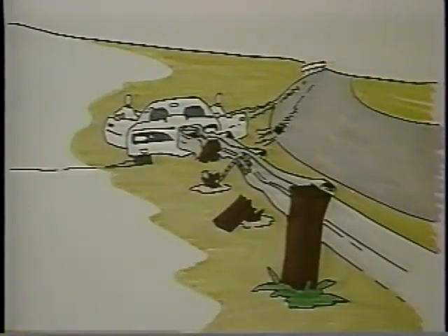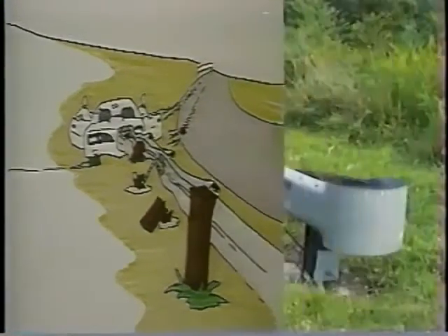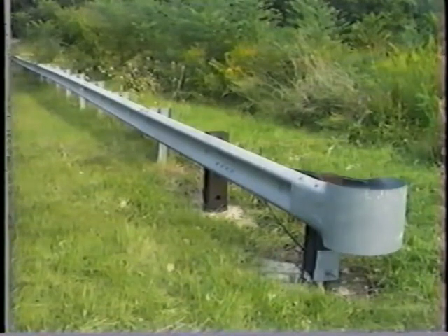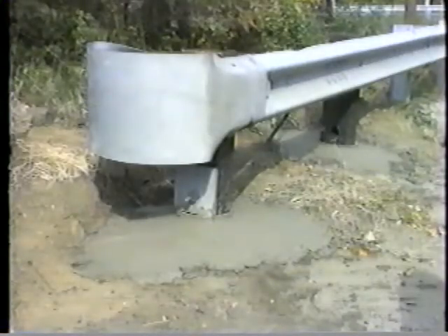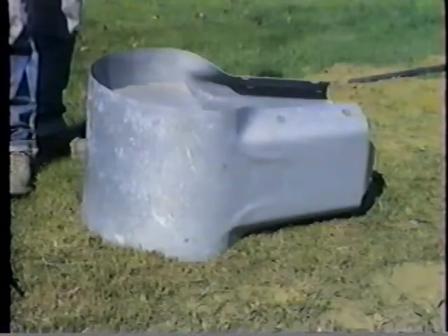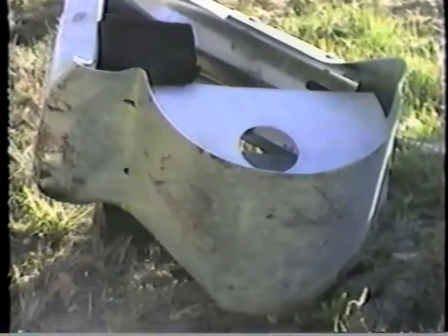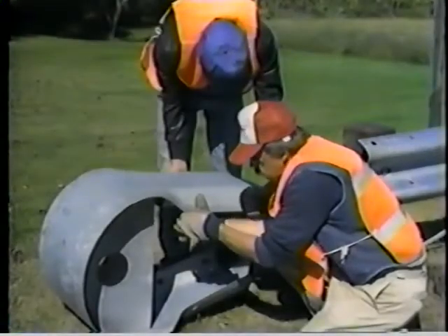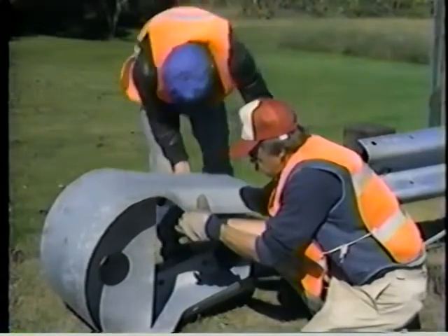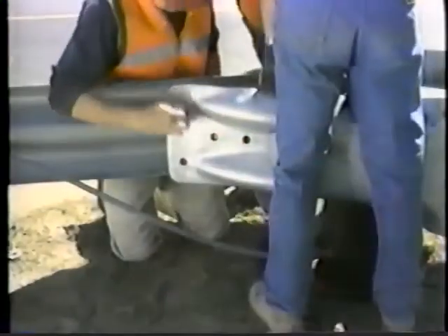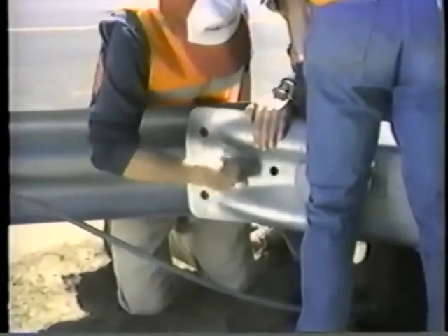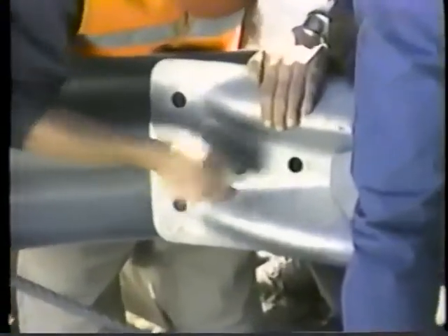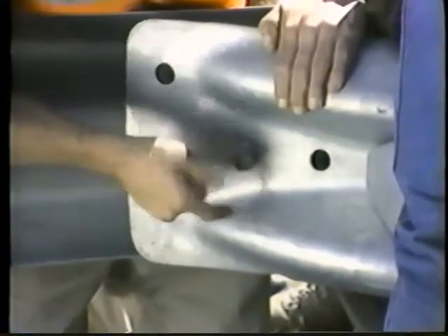Depending on the size, weight, and speed of the impacting car, beams in the end treatment continue to buckle until the vehicle is stopped. A bulb on the front of the system is intended to distribute a head-on collision's weight and force. It flattens out, preventing the W-beam rail from spearing the impacting vehicle. Here's a new bulb just prior to installation, and one that's been hit and done its job. To make sure this bulb functions properly, care must be taken to see that the wraparound connection on the back of the W-beam is tight and that all bolts have the right-sized washers. Otherwise, the bulb could tear loose on impact and the W-beam could spear the vehicle.